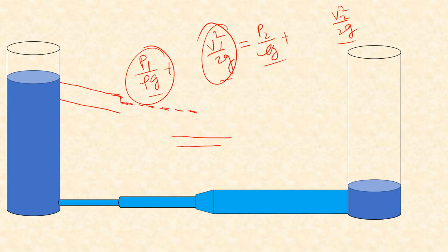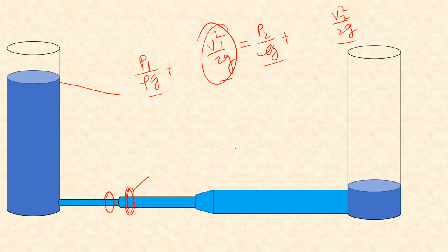Sometimes for a small increase in diameter, the pressure will also be smaller because some loss will be there, and that loss will be shared by the velocity and the pressure, and therefore how much will be the actual pressure drop or increase will depend from problem to problem. So in this case we can expect that the pressure head at this point will be smaller than pressure at this point. Similarly, pressure at this point may be smaller than pressure at this point.